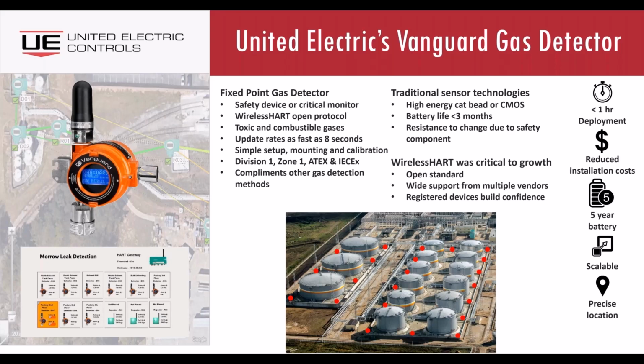Now you can start talking about deploying a lot of detectors, covering a lot of areas where maybe it wasn't cost effective to put a gas detector, and instead you just put mitigation should something else happen. Unfortunately, fire suppression is where you've got to put a lot more money in, because if something gets ignited, you have to get that under control quickly.